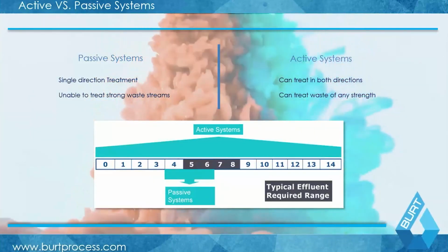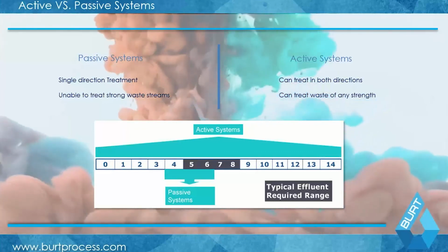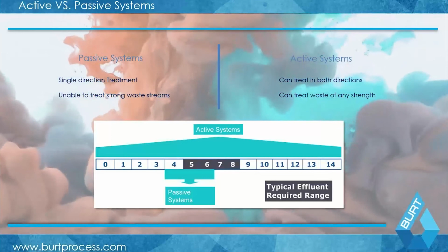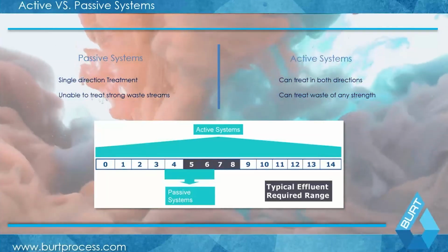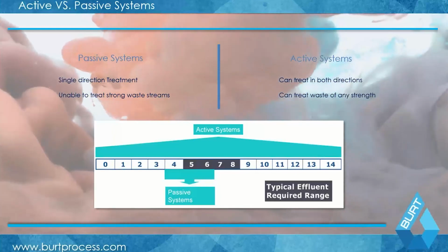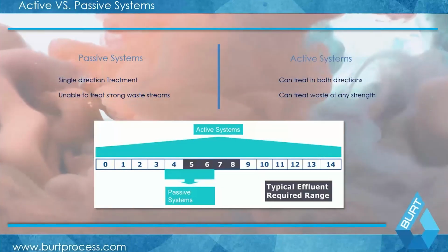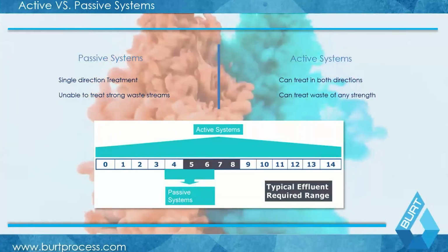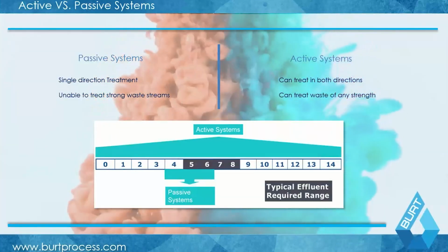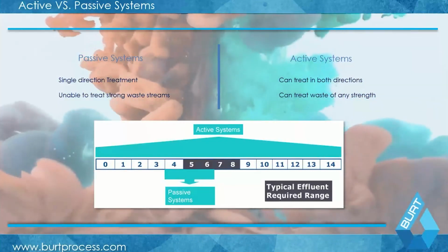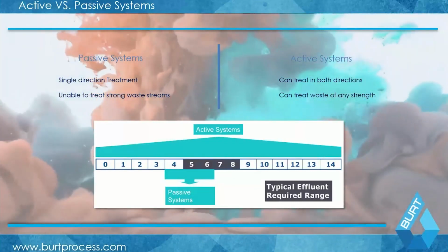Throughout history, pH neutralization systems have been around for about 50 years at this point or so. And by and large, going back in the day, they used to be considered very passive systems. I'm sure any of you familiar with pH systems are aware of the old limestone chip tank designs. These have been largely phased out, where you were using a medium of limestone, waste would come into the tank, you would settle for some amount of time, and you dissolve the limestone to neutralize the waste.